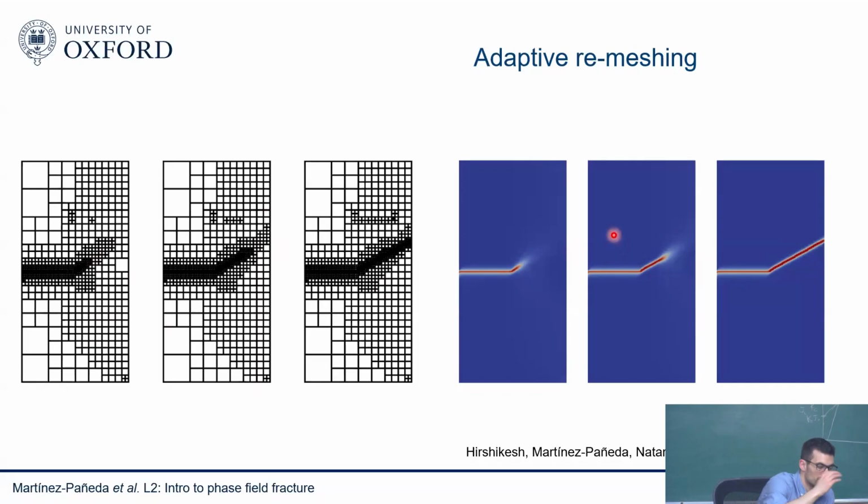Yes? This type of meshing I see is always rectangles in only one orientation, which means a crack face is always a staggered step. But in this method, you don't have to have full elements cracked or uncracked. This is the problem with local continuum damage mechanics. Here it is non-local. So the extent of where the crack is going to be distributed depends on the length scale. And therefore, you're not going to have elements that are either fully cracked or uncracked. You could have an integration point that is fully cracked and another one that is not, in that sense. So you don't have a staircase.